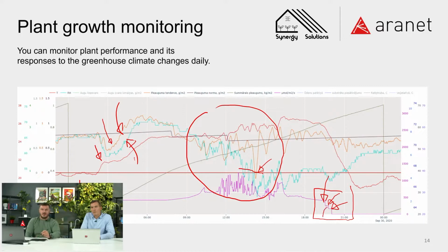And also with that one we have learned that if we switch interlight off before we switch the top light off, then we let more water get to the head of the plant, and we are increasing our relative humidity relatively slower, which has a better impact on the cucumber growth.